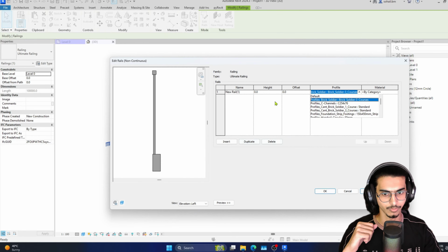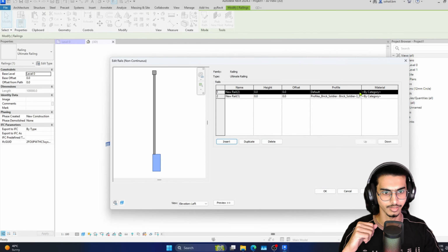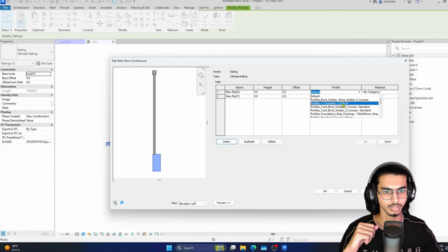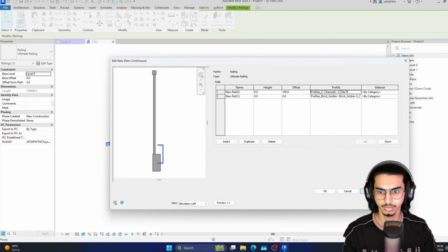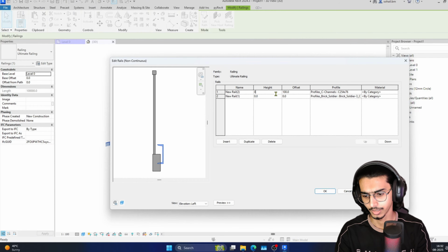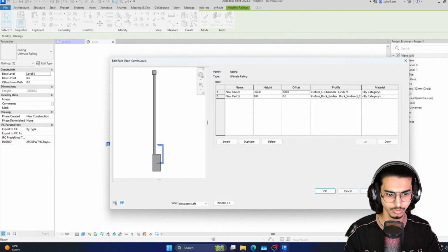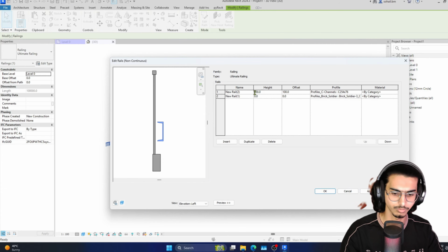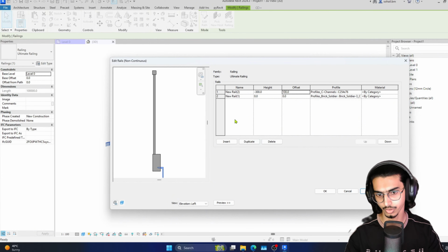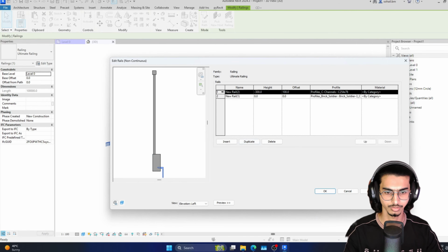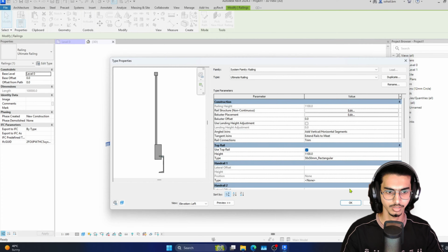And if I insert one, and this is going to be your pedestrian walk, I'm going to give an offset of 100. See, it is shifted here. I can give a height offset like minus 300. 100, minus 300, like this. So just imagine how it will work, how it is going to make such things. I'll cancel it.